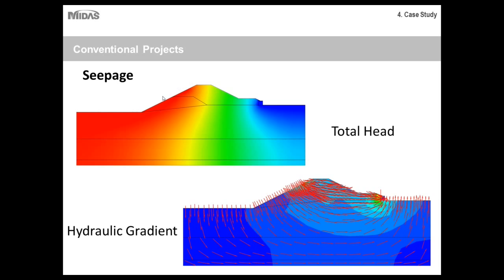So the water level would be resting on this side of the dam. Here the head would be larger, and then as you go to the right, to the empty side of the dam, the head would decrease. And you'd experience a great amount of seepage and a hydraulic gradient. Through numerical modeling, you'd be able to get your flow nets as well as your hydraulic gradients. If you double click on those arrows, you'd be able to get specific values for flow volume, flow velocity, etc.